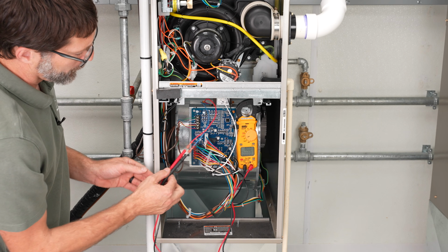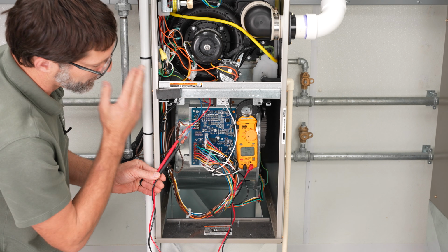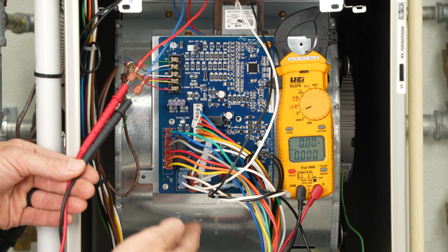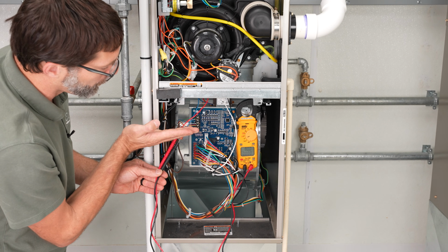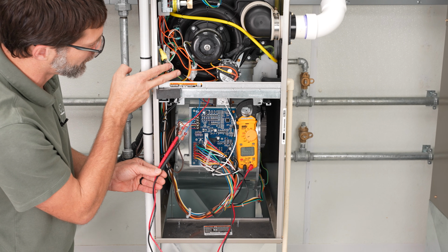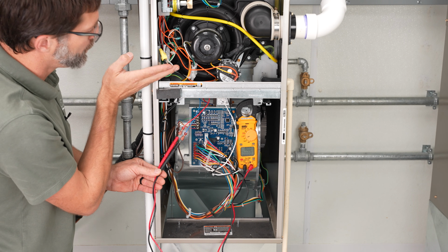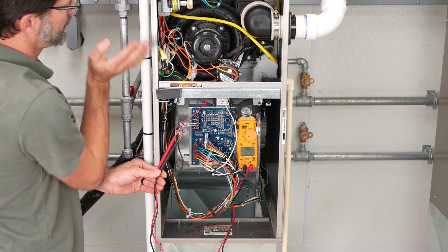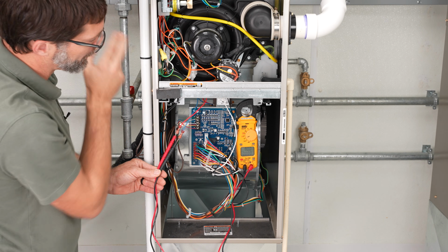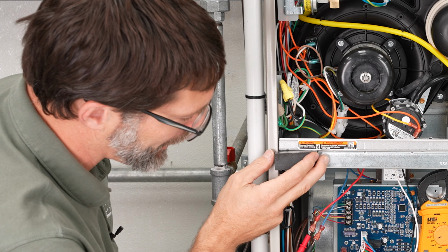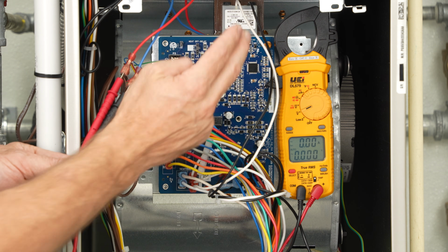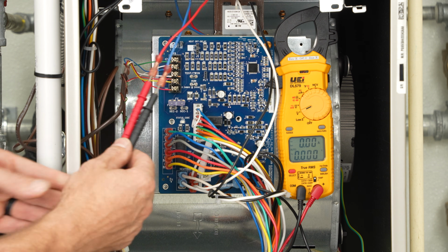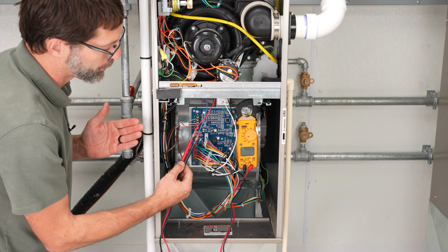So we either don't have power to the furnace, or we have maybe a loose connection down here, or we have a bad transformer. And so basically you just pick a point, which is the starting point up here. So we knew that we have a problem in this case upstream, so before the furnace. But if we did have power here and we did have power at the door switch, we had power down here, we would then start to move over to the transformer to see what the problem is. Maybe the transformer has been burnt out.